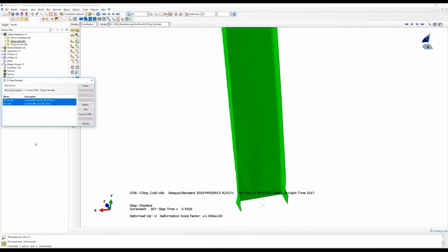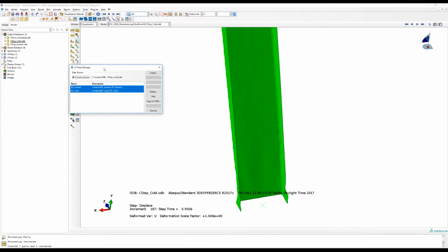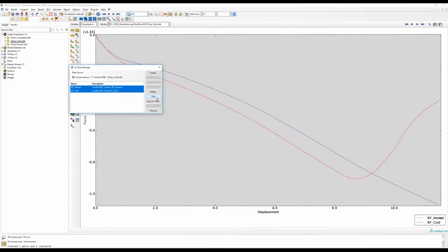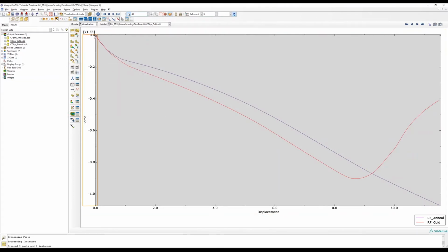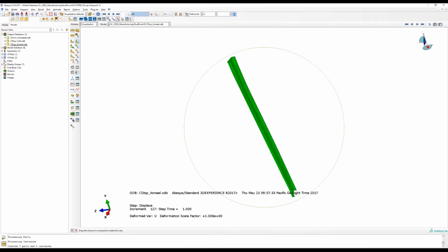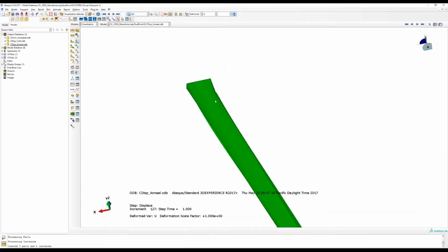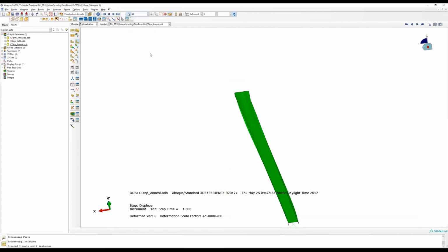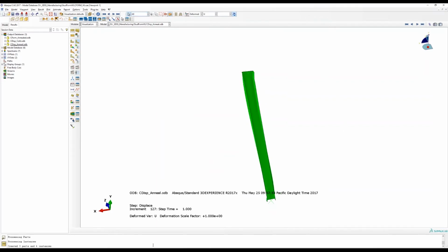And if we plot, we can track any of that type of data side by side. So here I'm going to plot what the reaction force versus displacement looks like, and that's how we arrive at the difference between the two. We can just go in and mine those results. They both are pretty severely distorted, but it just happens earlier with the cold worked beam at a higher load sooner. Which, if you're measuring to a narrow allowed displacement, is an ideal situation for a beam like that.